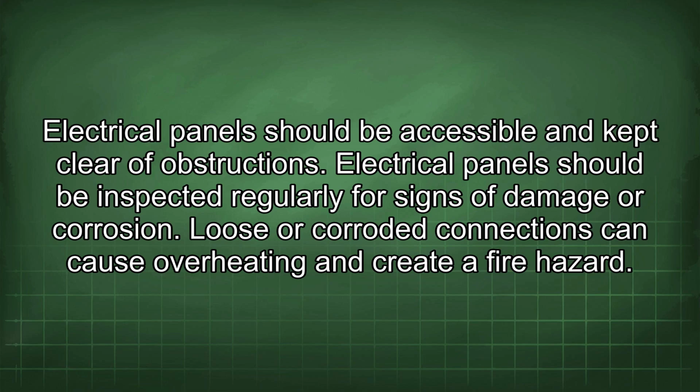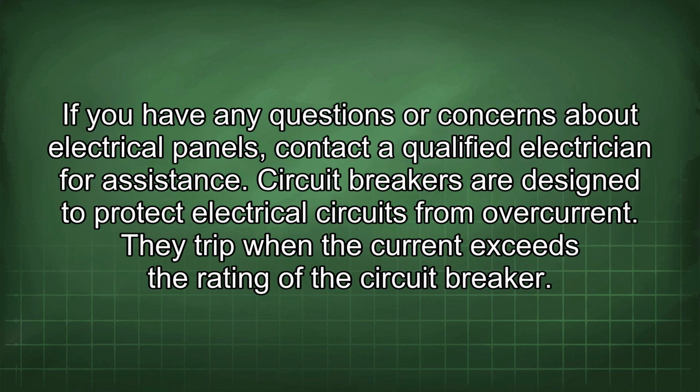Electrical panels should be inspected regularly for signs of damage or corrosion. Loose or corroded connections can cause overheating and create a fire hazard. If you have any questions or concerns about electrical panels, contact a qualified electrician for assistance.